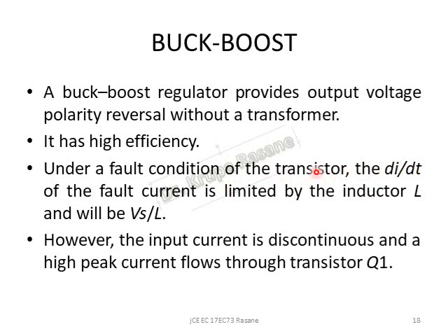But this di by dt of the fault current is limited by the inductor L, and this will be equal to Vs upon L. However, the input current is discontinuous. We have seen that no current will flow when the transistor opens up or in mode 2, and hence the supply current will become discontinuous and a high peak current will flow through the transistor Q1.